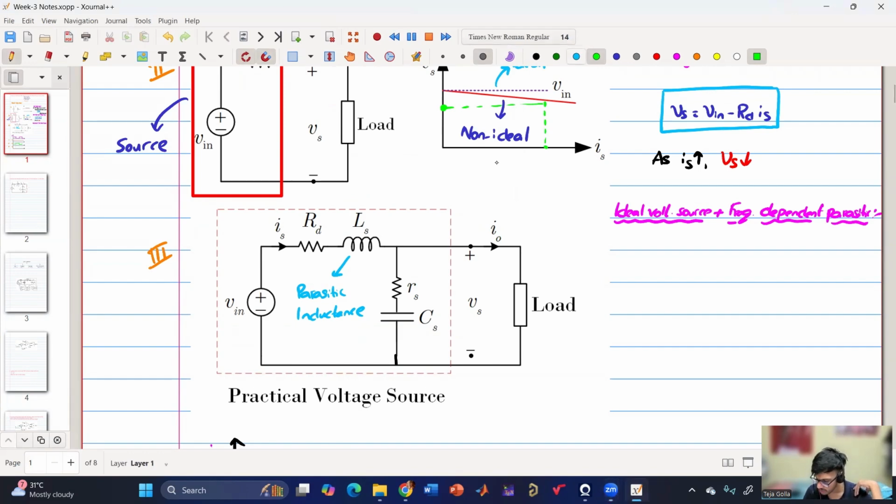Yes. So we need to see what the energy storing elements are. We have one inductor and one capacitor. So there are two elements, and both will contribute to two different terms. So we'll have two S terms. If we write in the Laplace domain, we'll have SL as well as 1 by SC, so we'll have S square. Because it is having two such elements, we'll have second order. However, if we have two inductors in series, then we can combine them as a single inductor. In that case, it will be first order, but here it will be second order.